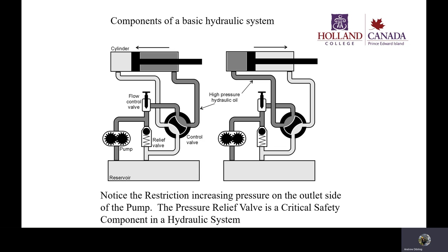There's generally a baffle or two in a reservoir to prevent gurgle loading, where the fluid will slosh, and that could end up with the pump sucking air in, which is a really bad thing. You don't want your pumps to suck in any air. You want to avoid that at all costs. And a lot of the design of pumps and the inlets are designed to minimize the possibility of sucking up air.